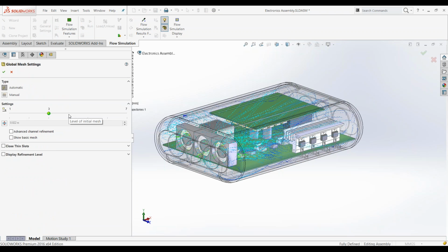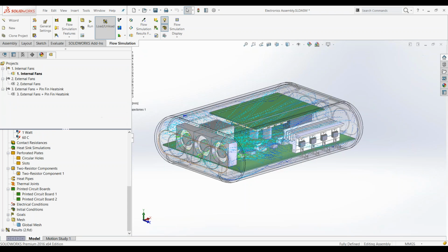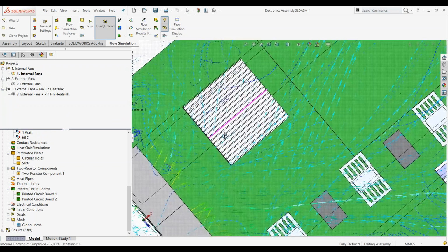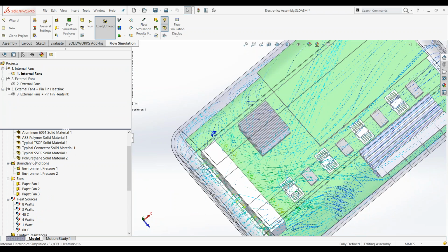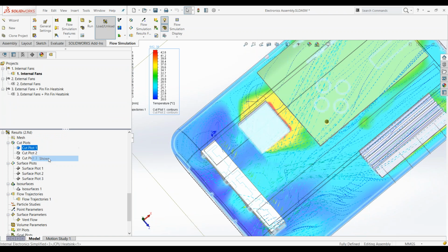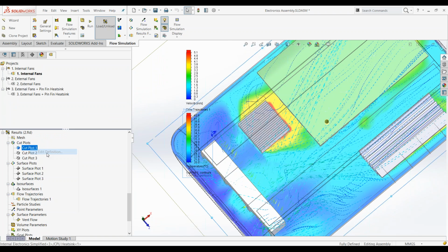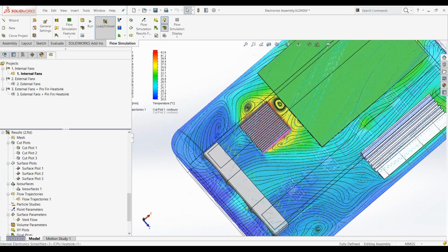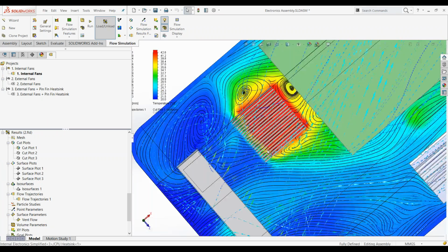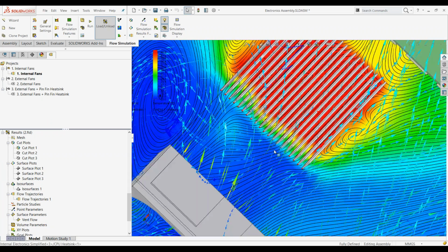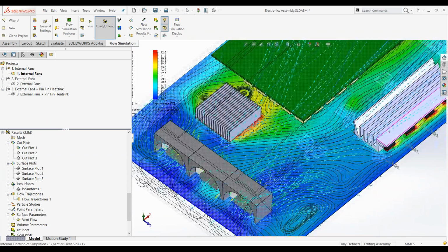Run the studies and look at the flow trajectories, to see if the flows are flowing through nicely, or even call out the color plots and add the streamlines to understand further whether the flow did go through the systems or not, to understand whether your mesh is good enough or not good enough.